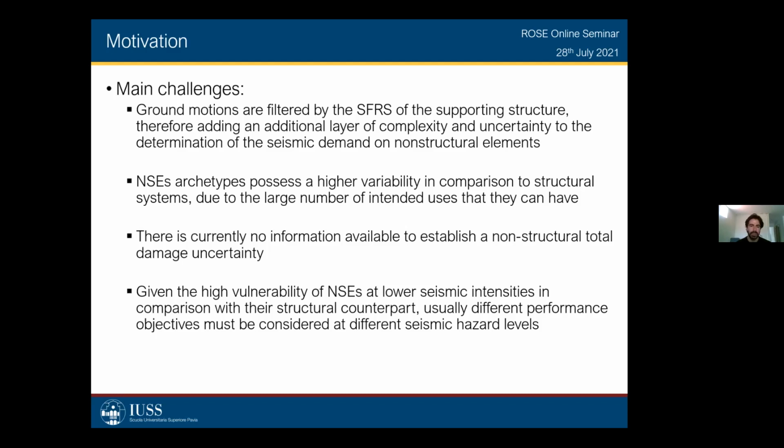Then we have that non-structural element archetypes possess a higher variability in comparison with structural systems, due to the large number of intended uses they can have. If you imagine, for example, structural systems, in the last decades of earthquake engineering, the community has come up with many systems, but at the end of the day, they look alike a lot. For example, you can have a moment resisting frame, you can have a shear wall building, or you can have a cantilever structure or whatever. But at the end of the day, the geometric characteristics of these systems don't differ a lot. They're more or less consistent, let's say.